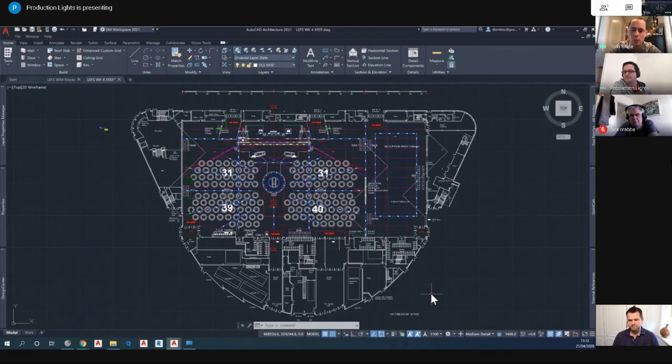I would agree fully with Tom. Out of interest, in 2021, which is the latest AutoCAD for PC, there's a feature where it will highlight the change in an Xref, which you could have done before, but this is a totally automated process. So if there was a new DWG that's been saved and it's a new Xref, it will pop up and ask, would you like me to highlight the difference between the two, the old and the new? It's an interesting feature, which I haven't gone into much detail on because it only launched 3 or 4 weeks ago. But otherwise, yes, I'd fully agree with what Dom said.